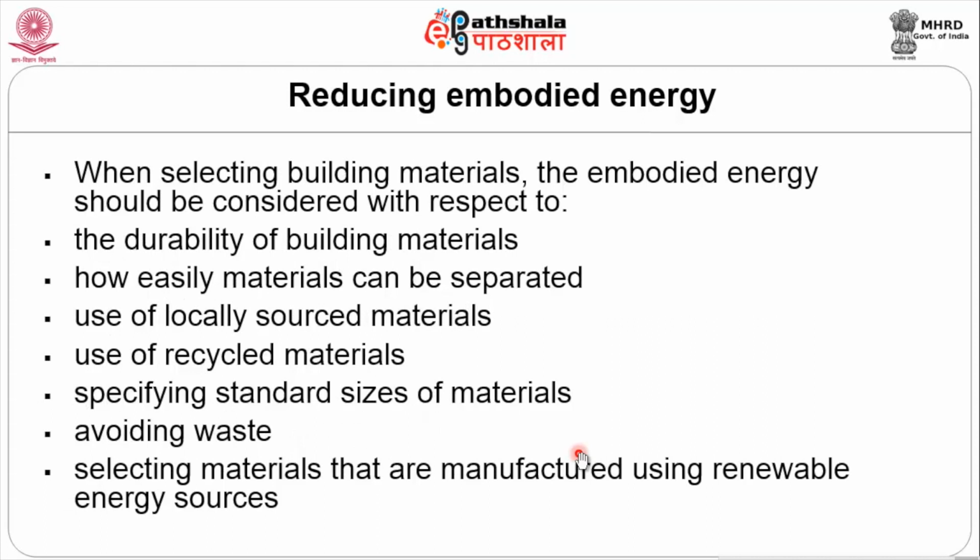When selecting building materials, their embodied energy should be considered with respect to durability, that is, the lifespan of the building materials, the quality associated with them, how easily these materials can be made available, and how they can be separated. The materials can be used locally, can be recycled in construction, and by specifying various standard sizes of the materials we can minimize waste.